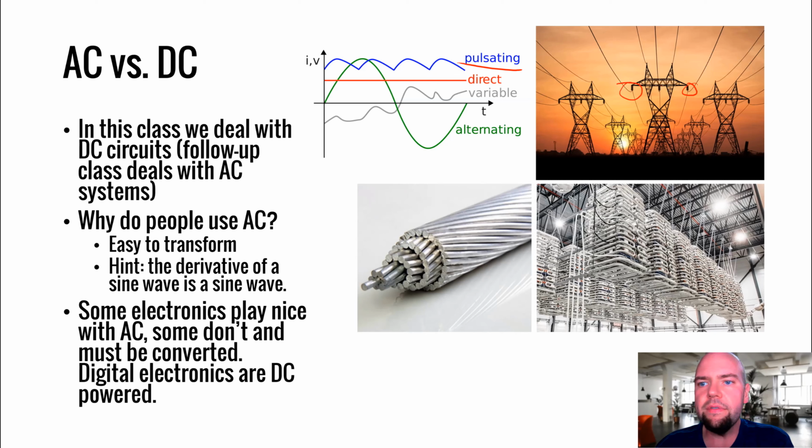The downside of high voltage is, as seen here, how does that song go? You got to keep them separated, right? If you have a 1,000,000 volt potential difference, and you let these wires get too close together, you're going to get a sparky lightning show, right? And so to avoid that breakdown, to avoid that arcing, you have to keep these conductors very far apart, and that means that when you drive down the highway, you see these giant towers with dangling conductors. They're really big.